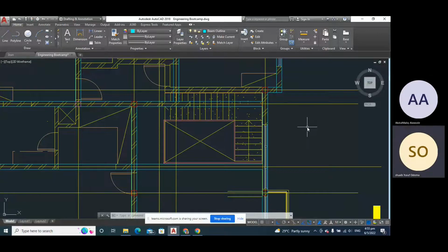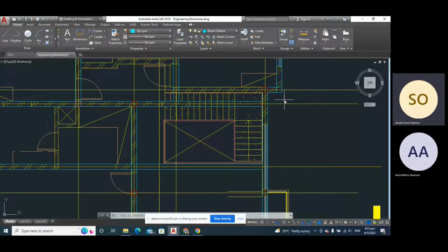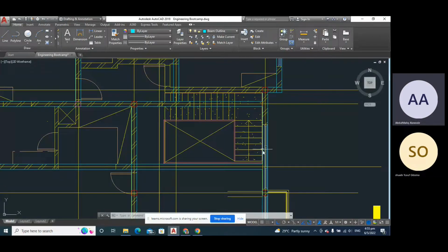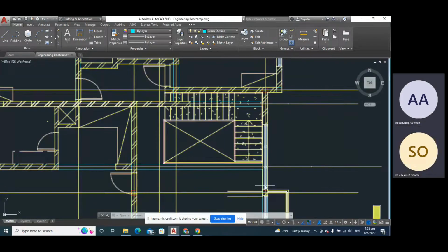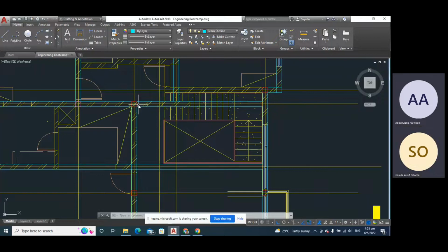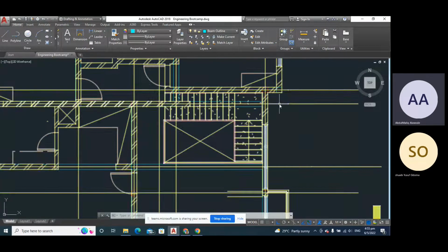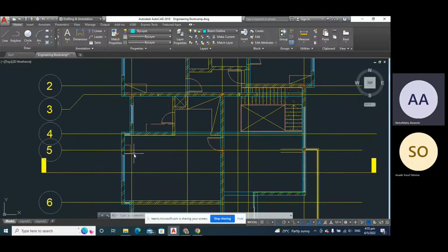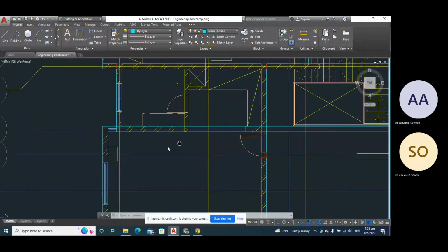That means the secondary will have to rest on the primary to help carry the load. That's good. In essence, when they are placing reinforcement, the bottom reinforcement of this vertical beam will be placed first. Then they will lay the horizontal one on it. Exactly. Thanks for getting that.